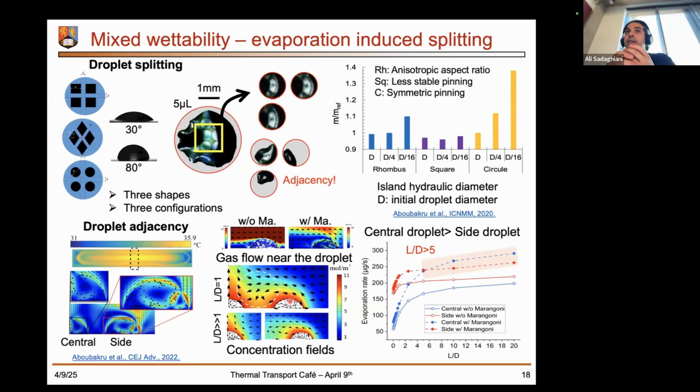So what I would do is have smaller islands, and the distance between them, I would start with a bit more distance. How much distance? I don't know, maybe 10 times, because in subatmospheric conditions, what we observed was for 5 to 10. Again, at subatmospheric, we have larger bubbles. So even 5 times the pitch size is not enough. Ooh. Okay, yeah, thank you for your insights. My pleasure.